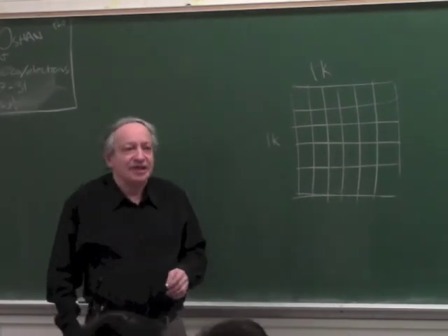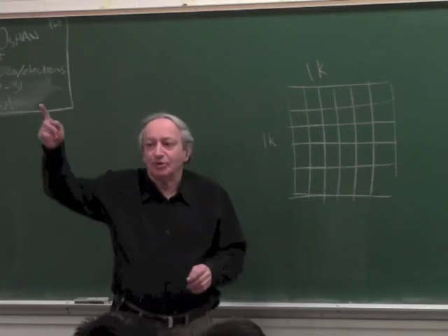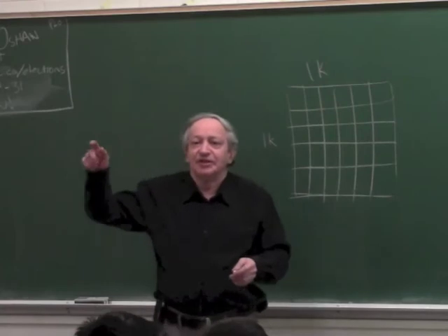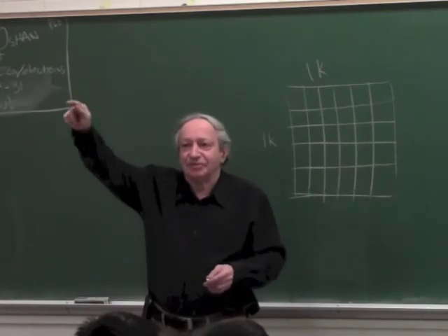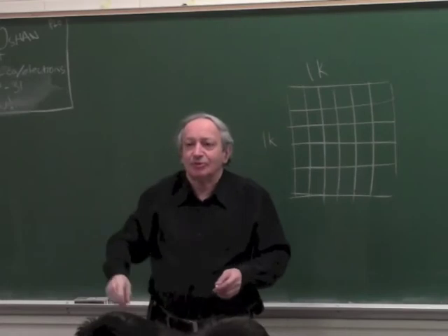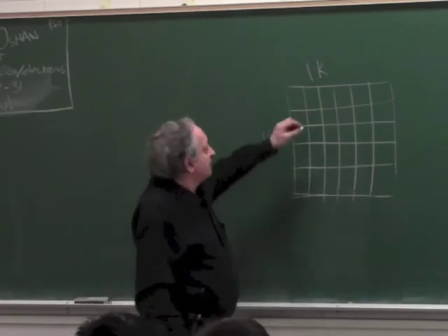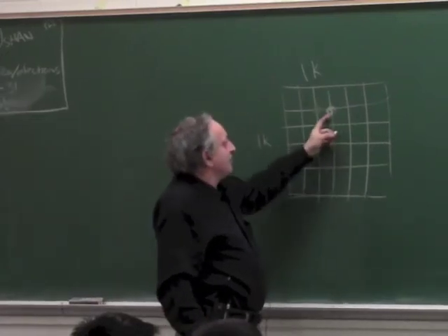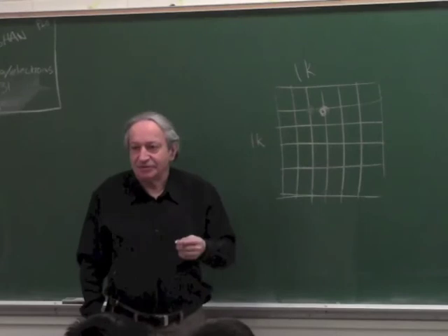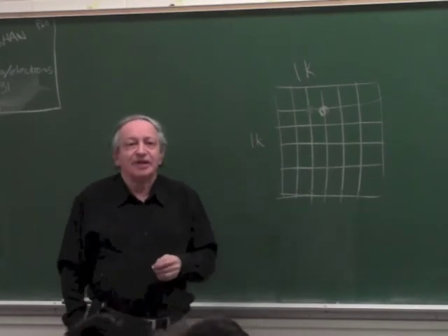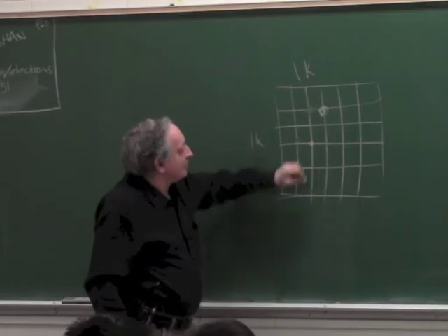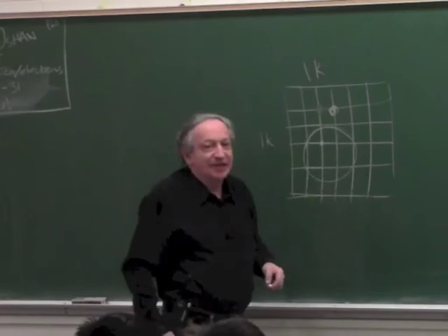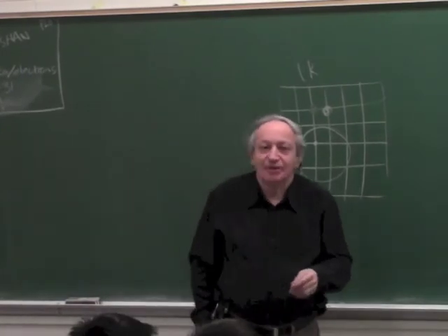Okay, so I want to track a laser pointer on the wall, or a tip on the robot, or the tip of a crane using a camera. So let's say I have a building crane, which I want to track exactly, the tip of the crane to 1 meter. So I put an LED at the tip of the crane, and then I see the image of the LED here. And then I track it simply by looking at which row and which column it is, if it's a 2D sensor. So the first question is, should I aim for the smallest, sharpest spot, or maybe it's better to have a bigger spot on the camera, even if it's a bit blurred? So, by now you should know the answer.